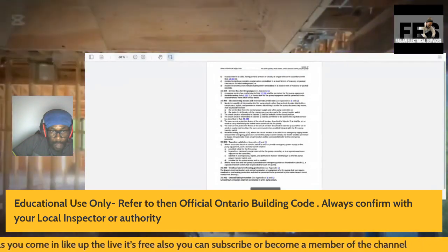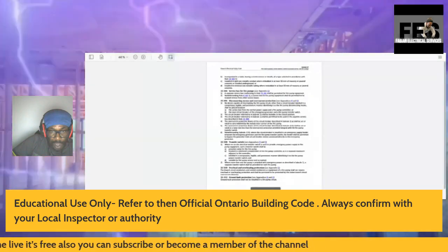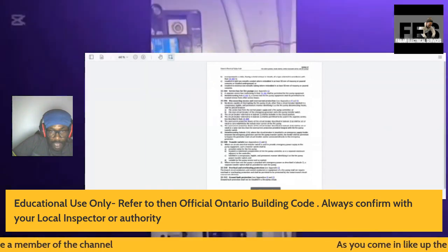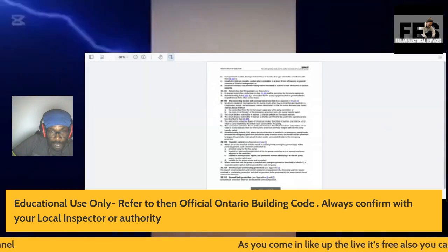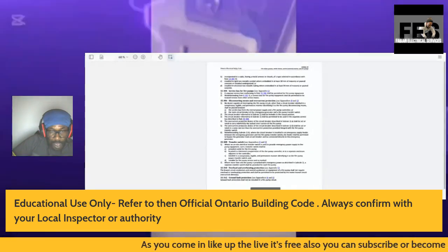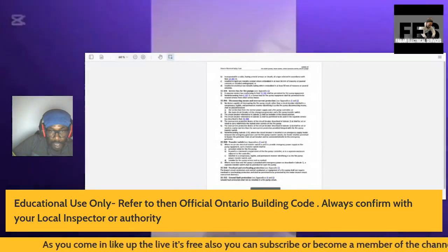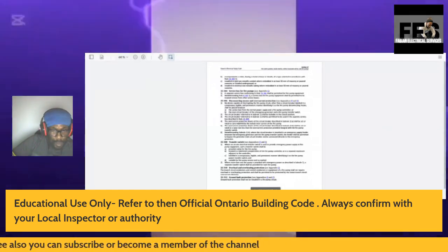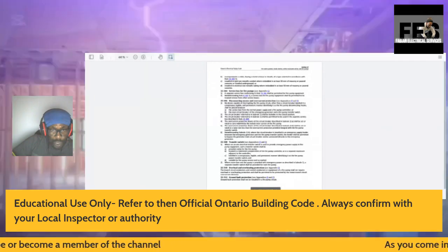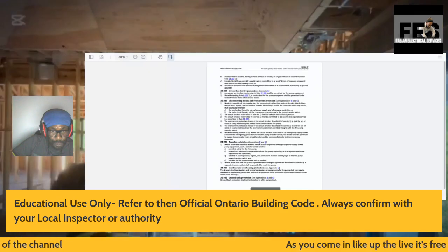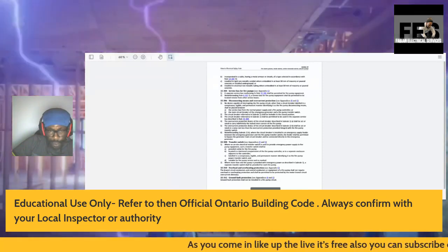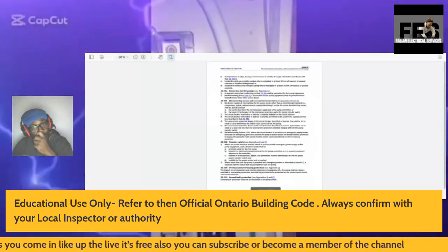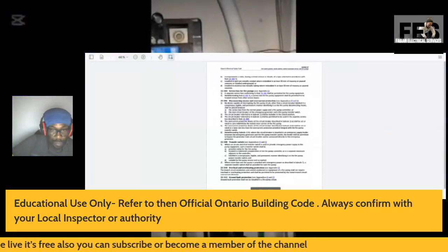Notwithstanding Subrule 1B, where the circuit breaker is installed in an emergency supply feeder between the emergency generator and the fire pump transfer switch, the feeder shall be permitted to bypass the generator main circuit breaker and be connected directly to the emergency generator. So again, this is the transfer switch rule when it comes to the emergency generators.